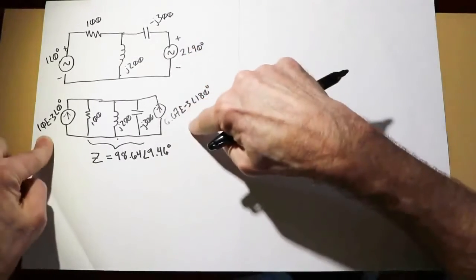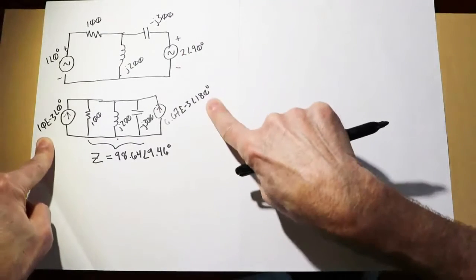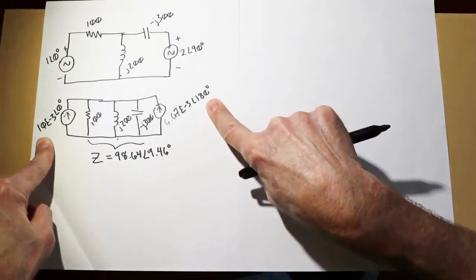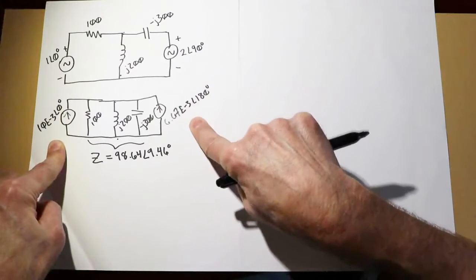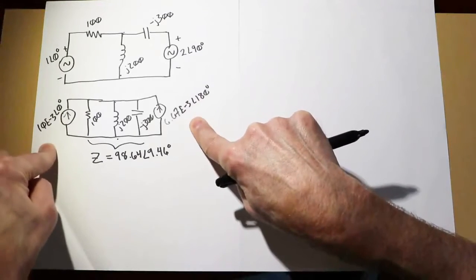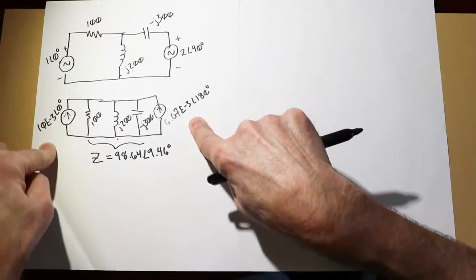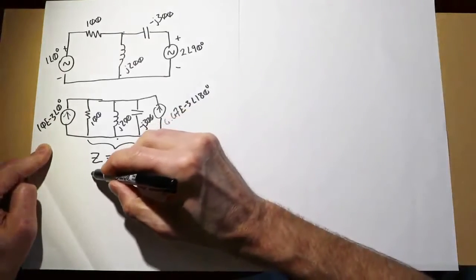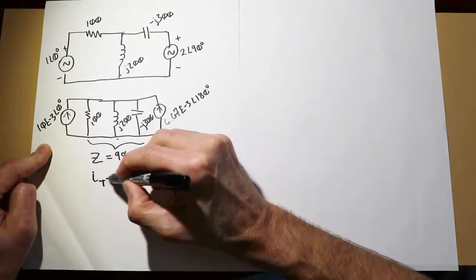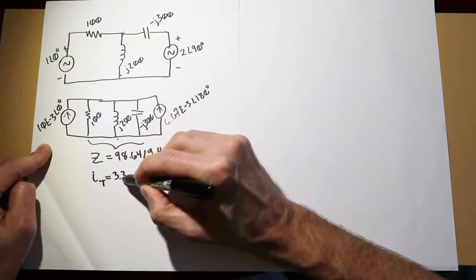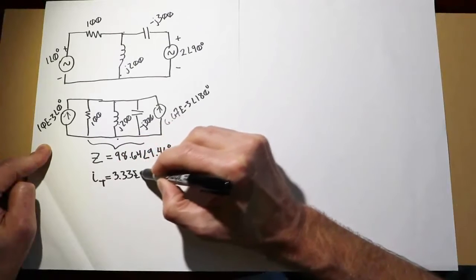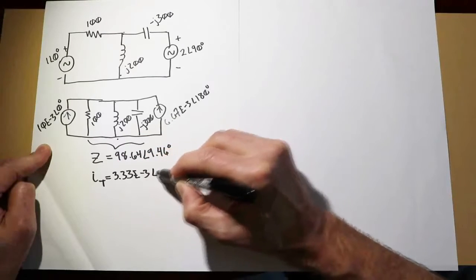Now, the two currents, when they combine, notice that this current source is 180 degrees out of phase with this current source, which basically means we simply subtract 6 2/3 milliamps from this 10 milliamp source. That's going to give us 3 1/3 mils. So our completed current, our total current, will simply be 3.33 roughly milliamps at an angle of 0 degrees.